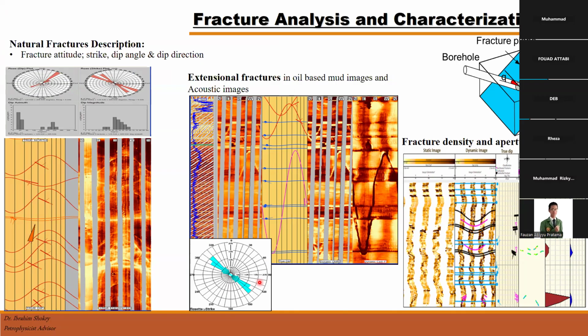At the beginning, the fracture definition: it is some sort of discontinuity plane as a result of exceeding the tensile strength of your rock. If the stress is increased further than the displacement of your rock, it will convert your fracture into a fault.